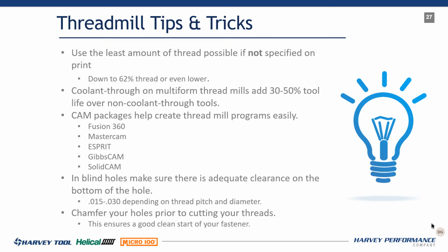So programming, right? CAM packages help create thread mill programs. We can do it longhand. We can G and M code it. And I'll tell you what, when I was G and M coding thread mills, I was so lazy. I didn't do an arc in and an arc out. I dropped down in my hole, I came over in an XY straight line, I engaged in my material and I circle interpolated out, which some of you guys might be doing. And you're probably having good success with that. It will fatigue tool life, which is why you want to arc in and arc out.